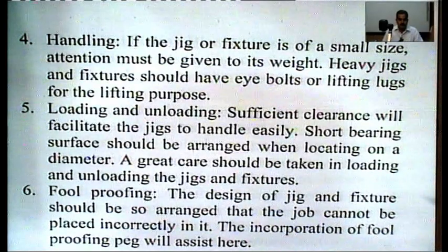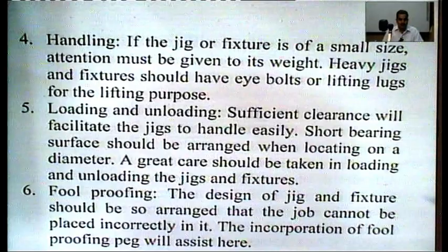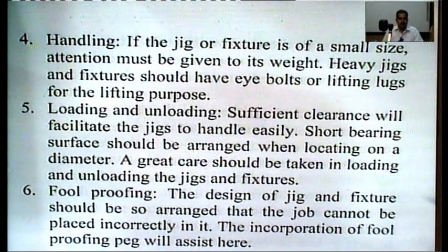If the jig or fixture is of small size, then attention must be given to its weight. Heavy jigs and fixtures should have eye bolts or lifting lugs for lifting purposes.